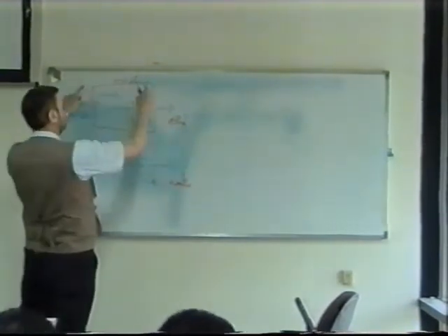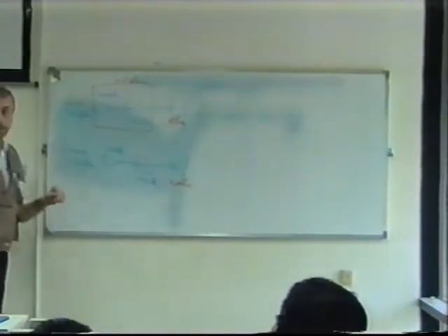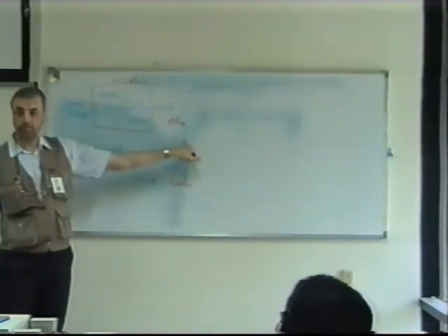So that's the first thing we can do. We can say that this is like one unit with a gain of 40, just by using addition and subtraction. We don't have to bring it to a ratio. It's not necessary. We can just use addition and subtraction. Here we have a gain of 40 dBs. Now, it so happens I've given you the input power in dBm. That's a big advantage. You don't have to change that to watts, because I don't want the output power in watts, I want the output power in dBm.